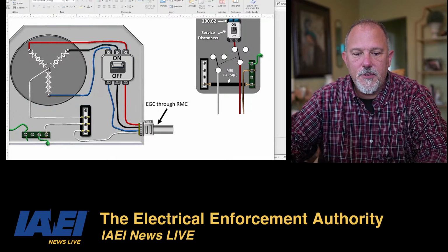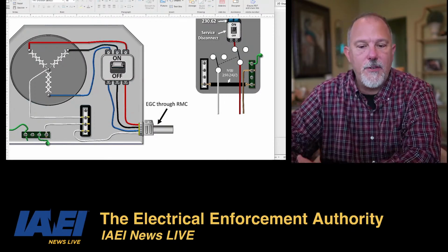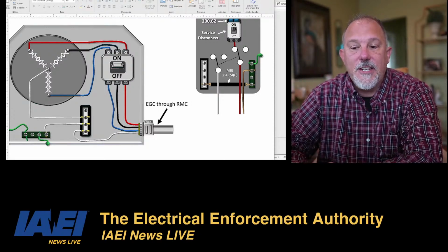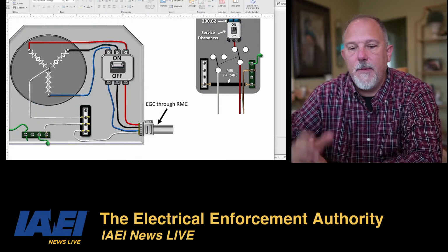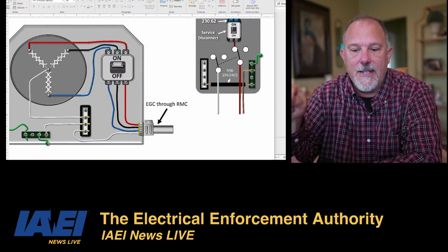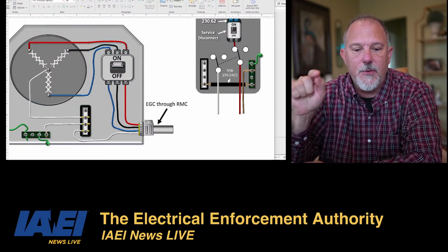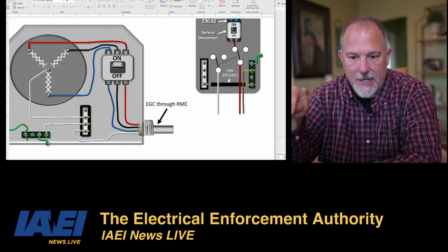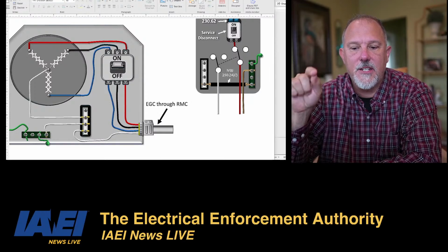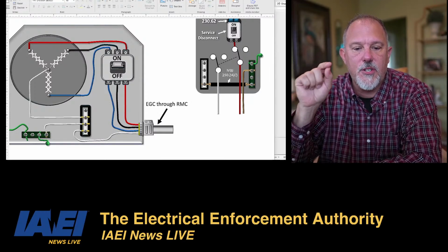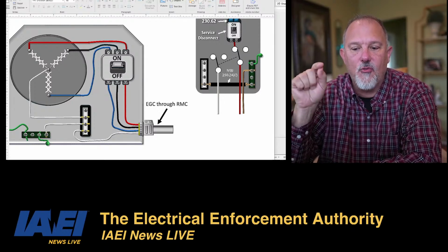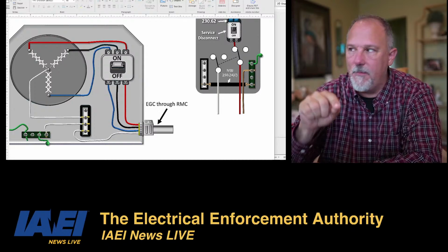Okay, informational note number 1 says an alternate AC power source, which might be a generator, such as an on-site generator, is not a separately derived system if the grounded conductor is solidly interconnected to a service-supplied system. An example of such a situation is if the alternate source transfer equipment does not include a switching action in the grounded conductor that allows it to remain solid. So,